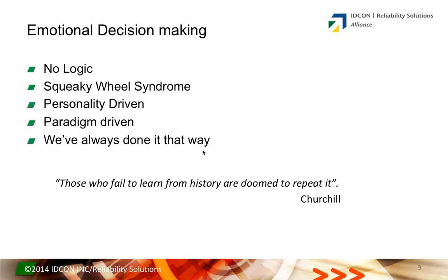The whole purpose of root cause is to do this, which is de-emotionalize the decision-making process. A lot of facilities I go to, you know, something bad happens, and immediately there's some kind of knee-jerk reaction, often involving, let's do a whole bunch of PMs on this machine because it's failed and we don't want to be bitten by it again. The problem with that is there's no logic, there's no science to what you're doing or why you're doing it, and very often it's personality driven.